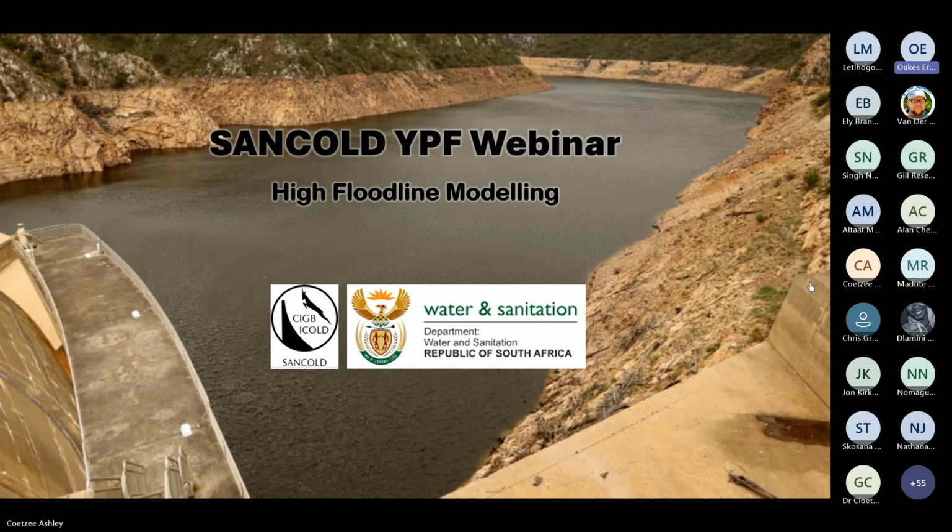And then, in terms of making sure that the cross sections are perpendicular to the flow, if you were to do it manually, it is actually a subjective approach. Based on my own experience, the contours can give you an indication as to where the water is going to go. If your area widens out and then comes back in, you have to draw your cross sections perpendicular to the flow, or the direction of the river, almost facing out in a sideways direction, and then they bend and adjust as the topography becomes steep again. It really is a subjective thing, and from my own experience, you get better at it the more you do it. So that's a point regarding those 1D cross sections. Thanks.